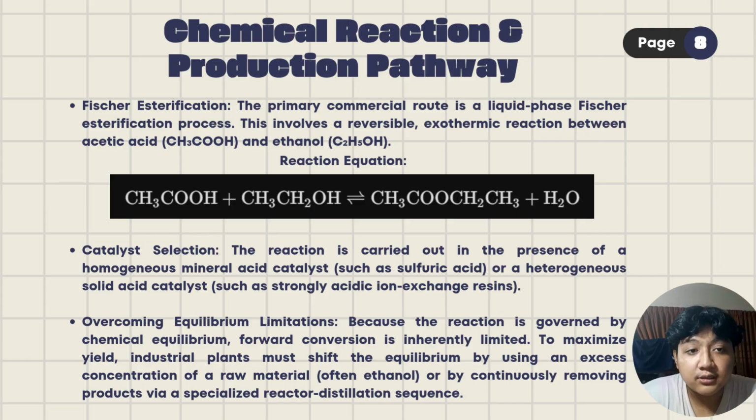To increase the reaction rate, an acid catalyst is required. Industry commonly uses sulfuric acid as a homogeneous catalyst or acidic ion exchange resins as a heterogeneous catalyst.